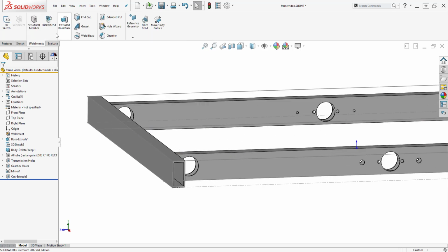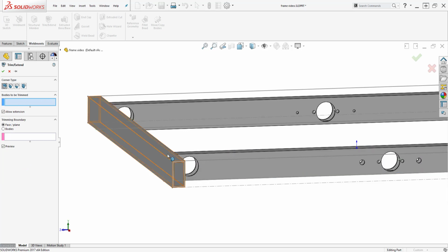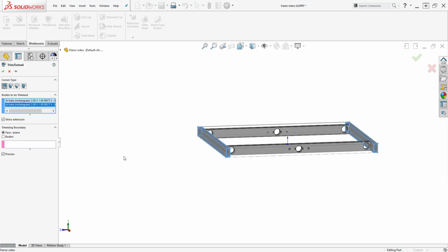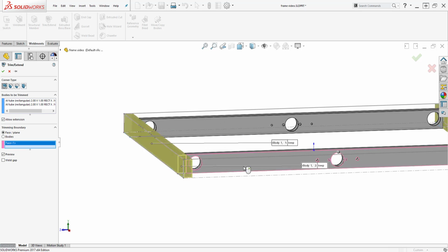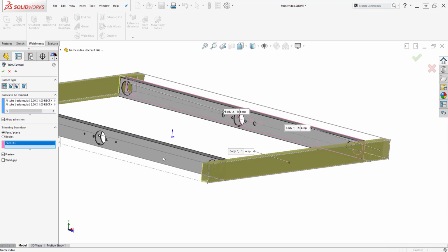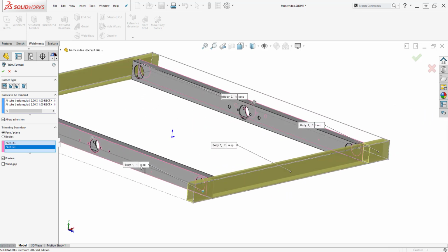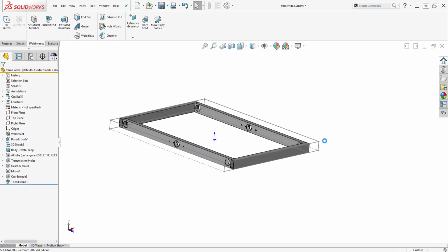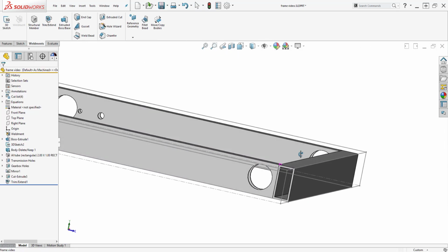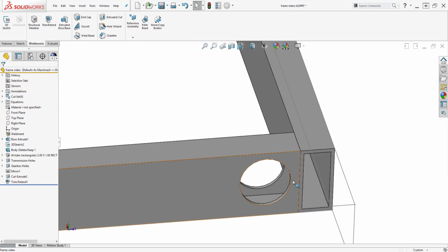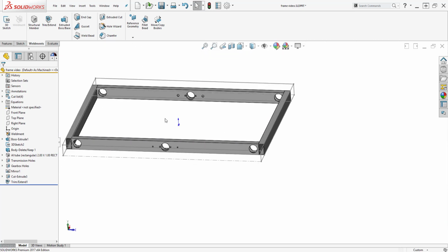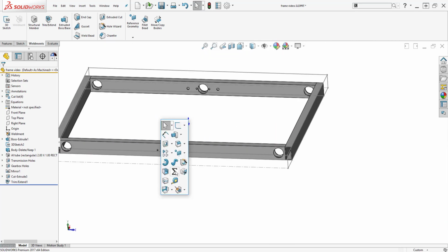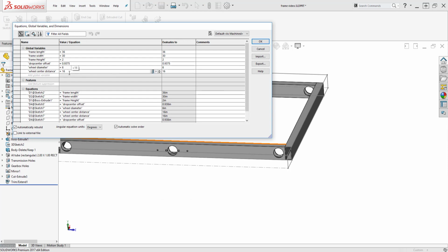Now, being this close to the end of the tube, the Versa block is not going to be able to reach because it's going to hit the tube and you're not going to be able to center the bearing and axle through the hole. So I'm going to go ahead and change that back to a different wheel center. Again, if you're using a chain calculator for this, you're going to know exactly where your wheel center needs to be. I am mainly showing you guys the calculations so that you can make your design changes quickly and get to a finished chassis a lot faster. And later on down the road, if you're attaching other mechanisms to your robot, you come back and you find that, oh, this needs to move or this needs to change, it'll be a lot easier to do so.